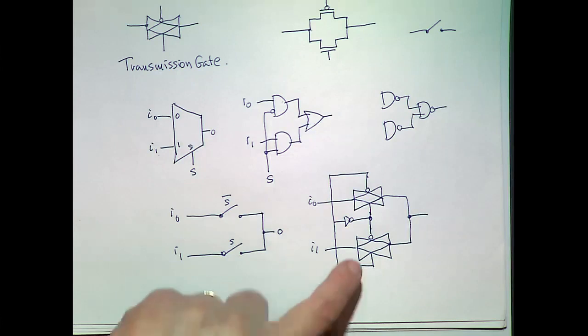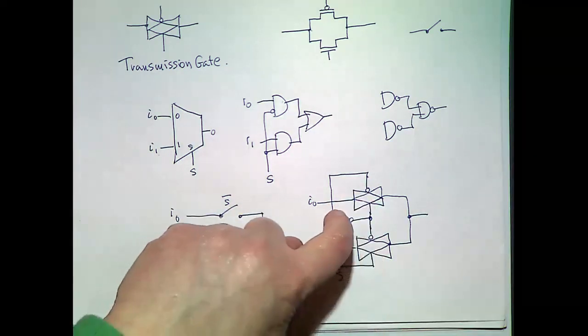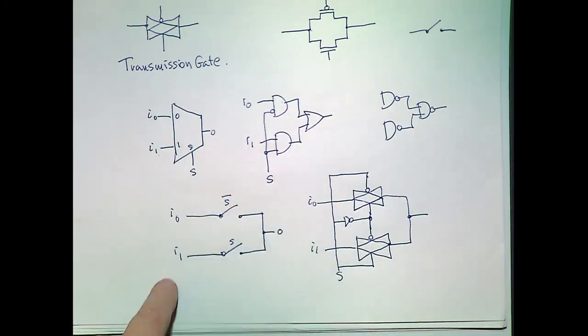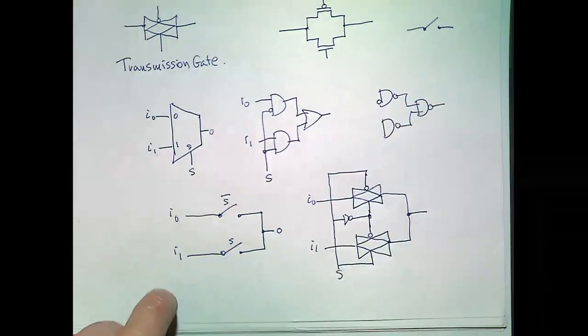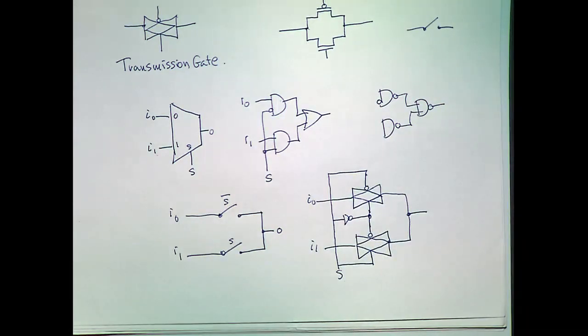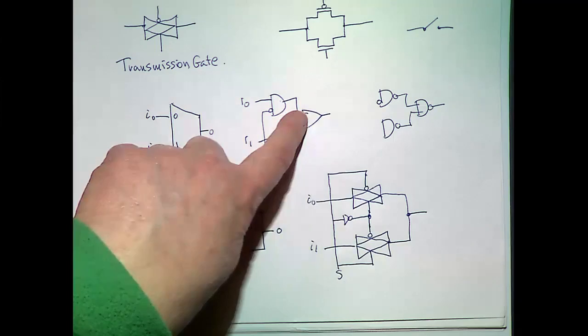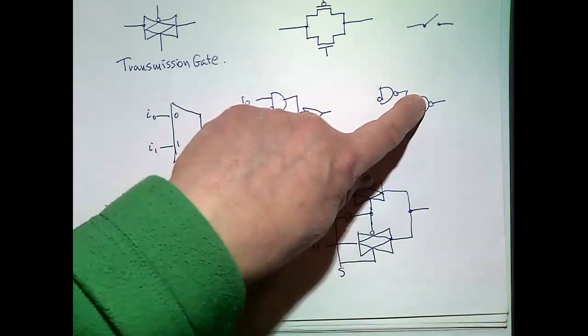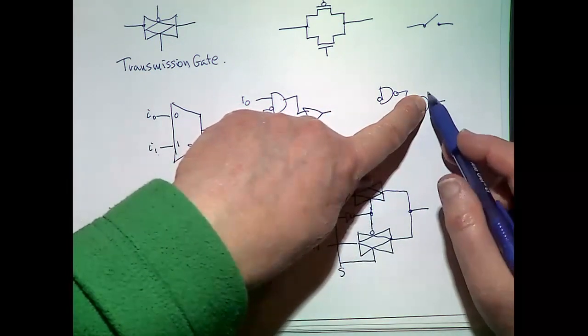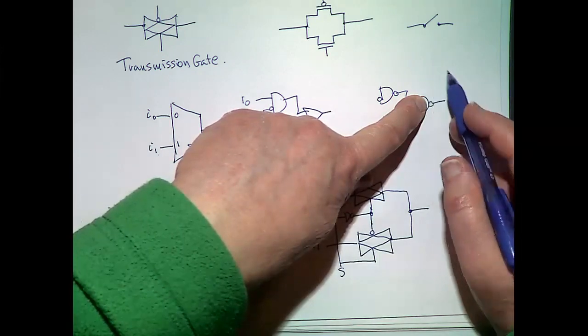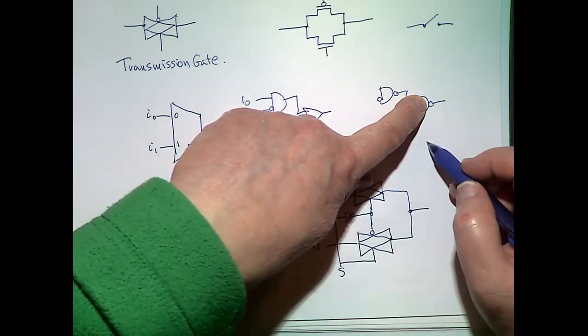6, right? 2 plus 2 plus 2. Here we had 12. Actually, I should count an extra 2 for inverting that input, if you like. So that's 14. Now, there's one very key difference here between these two circuits, and that is this is a NAND gate, which means that this output is actually being pulled up through two transistors or being pulled down through the two transistors.